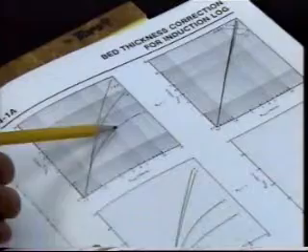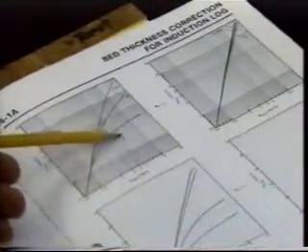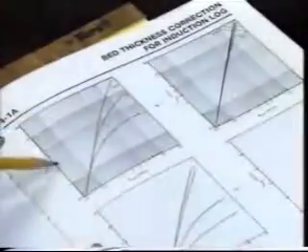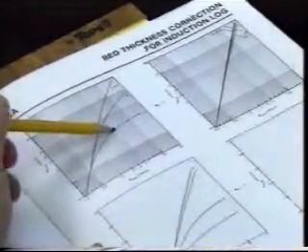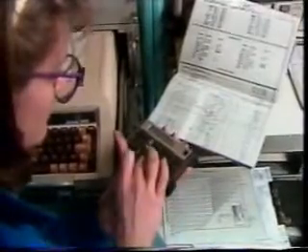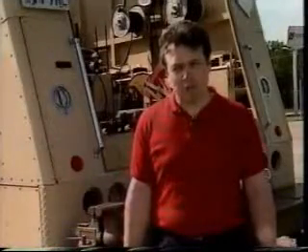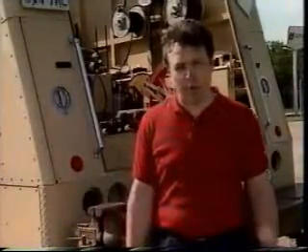Another correction for induction tools is for bed thickness, since deep horizontal investigation leads to poor vertical bed resolution. The corrections for bed thickness are carried out with charts. By plotting bed thickness against measured resistivity, an improved resistivity of the center of the bed is determined. Other corrections for induction logging include hole signal and effects of drilling filtrate invasion. Like most logging tools, the induction has a two-point calibration.